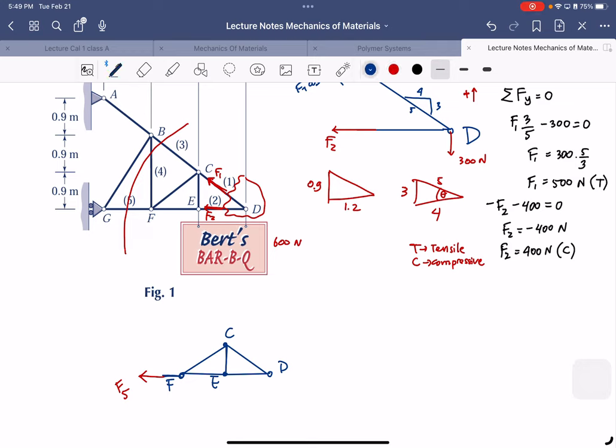And then this F should have a member here, but let me just cut that out and write it as a force, that is F4. And then the other member is on here, and we can give it F3. Okay, that's how you do the free body diagram. The free body diagram depends on what we need to observe, what significant forces are in the picture.